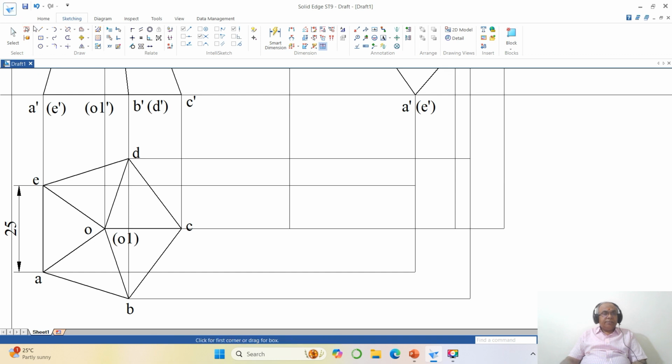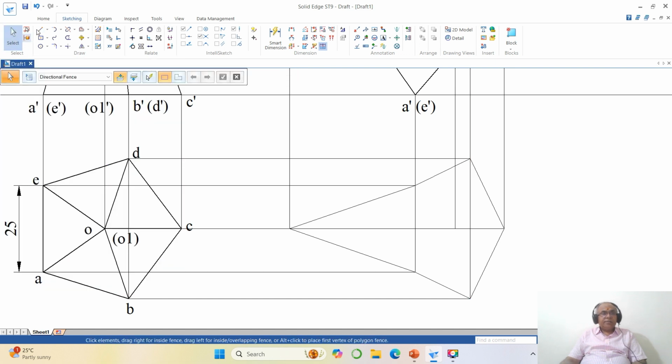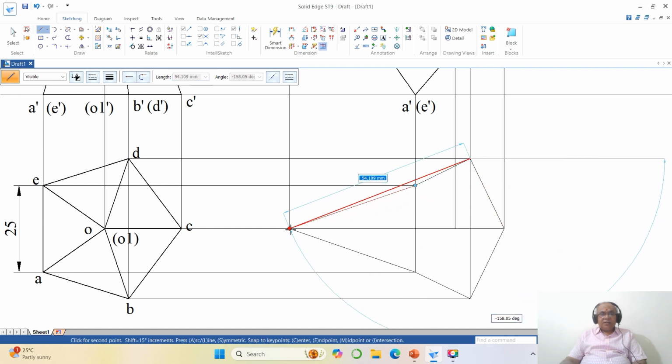Now go to the line command, draw a line from endpoint to this endpoint to this endpoint to this endpoint. Then you take this endpoint. All these things have to be done by thin only, don't make them dark. So enter. Again you go to line and you take this endpoint to this line, and similarly to this line. Okay. Now we have the drawing with me.